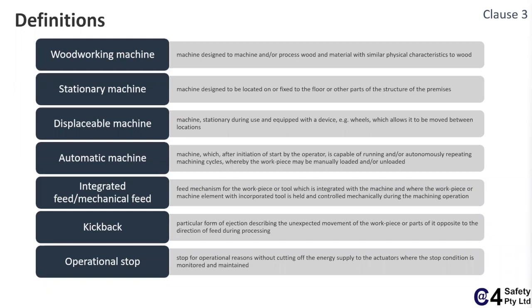Another one on there that was really interesting was kickback. Yes, I know Frank and I talked about that. So, kickback is absolutely relating to projectiles from the machine. And there's a number of ways of feeding material into these machines, either in the same direction as the blade is turning or opposite direction to the way the blade is turning and so on. And how do you control kickback in the best possible way? That's really what the specific standards talk about. But that's a very important part in terms of a hazard.